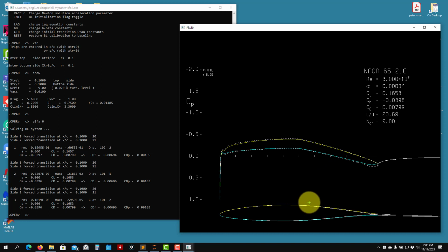it will occupy a large percentage of the airflow, and they can propagate and then they burst, and you lose lift and increase drag. Okay, so you see that it's an artificial mechanism just to trigger turbulence. Eliminate that, you are going to increase drag, but well, you are getting rid of that bubble.